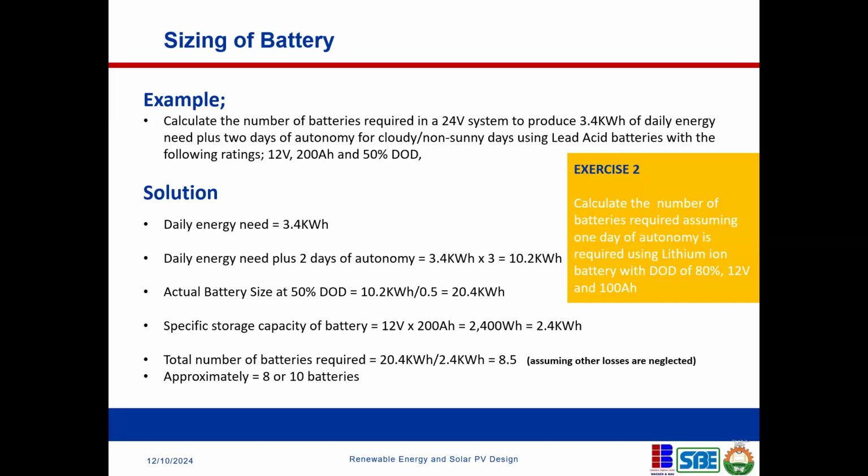So I want to believe that we all understand it. This is how you size your battery. You need all this battery technology information to be able to do this calculation. You need to know what depth of discharge you want your battery to go to, what the voltage of the battery is, and what the amp-hour rating of the battery is. Then you can do this calculation and size your battery.